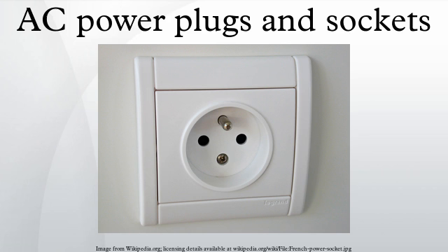Large appliances are usually sold with Schuko plugs, so 16A non-rewirable plugs are usually used only in adapters and power cords. Those appliances are always earthed, so unearthed 16A plugs are now very uncommon, and only a few brands still sell them in rewirable version.